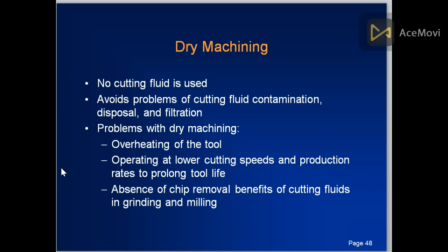Problems with dry machining are overheating of the tool, operation at lower cutting speeds and production rates, and absence of chip removal benefits of cutting fluids in grinding and milling. When the term dry machining is used, there is no lubrication or less lubrication.